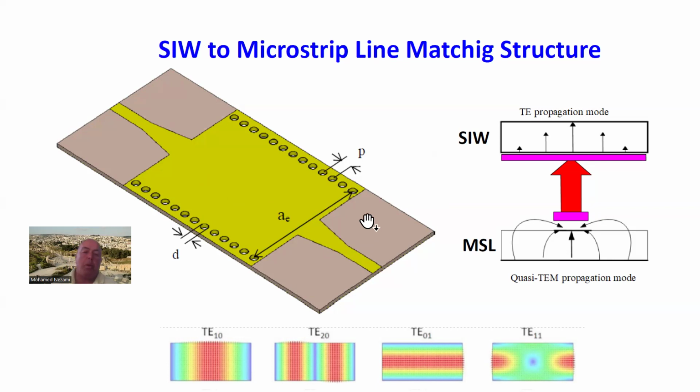Now, a lot of times, just so that we can reduce the development time, we go linear from this point to that point. We just figure out what is the width that has to be here and what is the width that we have for a 50 ohm line on this substrate, and we shoot straight, just a linear line, between these. This would work for most frequencies.